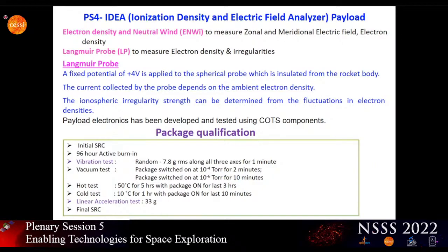Once the payload is able to survive all these things, you can be confident that the payload will indeed work in space, because there is strong vibration as the PSLV is lifting up. And also there will be very strong shocks that will come when stages are getting separated. So that is why all these tests are required, and also to see the survivability in hostile conditions, if at all it goes into that kind of a domain. And the final SRC will be done, where it will be further tested that the payload is indeed working.